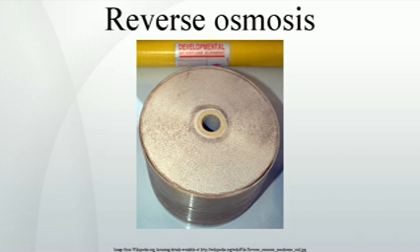In the normal osmosis process, the solvent naturally moves from an area of low solute concentration, high water potential, through a membrane, to an area of high solute concentration, low water potential. The movement of a pure solvent is driven to reduce the free energy of the system by equalizing solute concentrations on each side of a membrane, generating osmotic pressure. Applying an external pressure to reverse the natural flow of pure solvent, thus, is reverse osmosis.